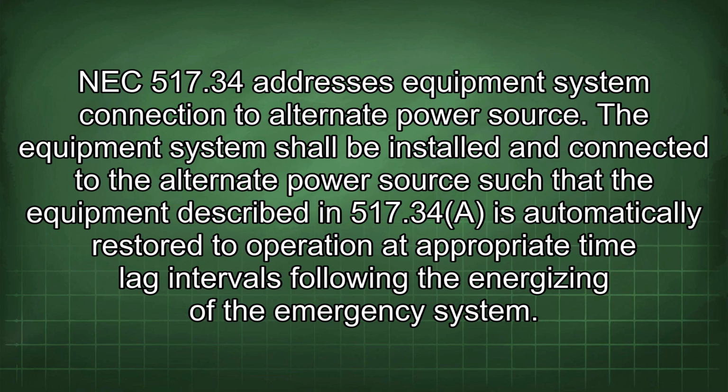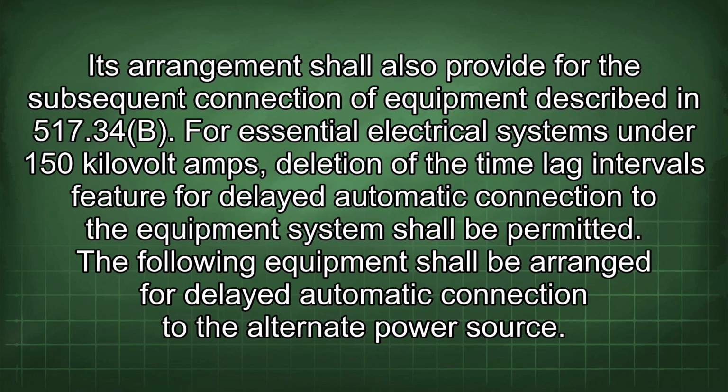NEC 517.34 addresses equipment system connection to alternate power source. The equipment system shall be installed and connected to the alternate power source such that the equipment described in 517.34 is automatically restored to operation at appropriate time lag intervals following the energizing of the emergency system. Its arrangement shall also provide for the subsequent connection of equipment described in